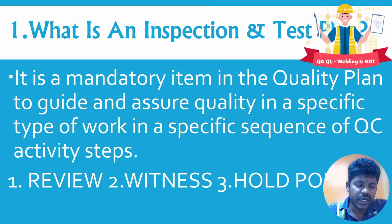That is called a witness. And hold point: you complete the work and offer it to the TPA, third party, or client. They want to come and check that joint, and if they accept and approve it, only then can you go forward. Otherwise you don't go forward. The job is just held, that is a hold point. These three things are what matter for the ITP.